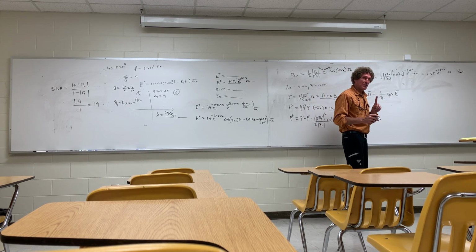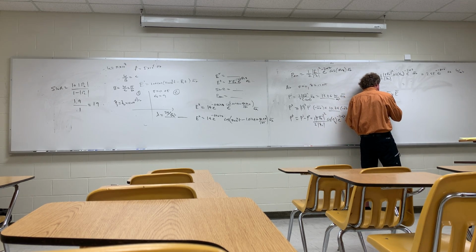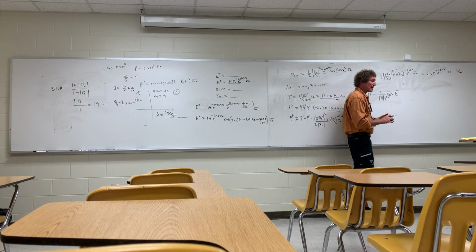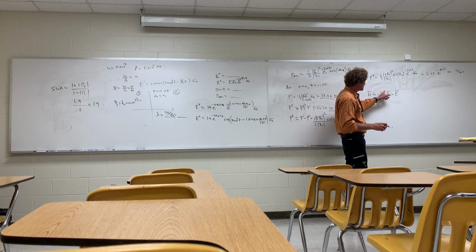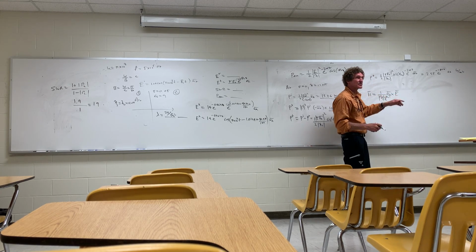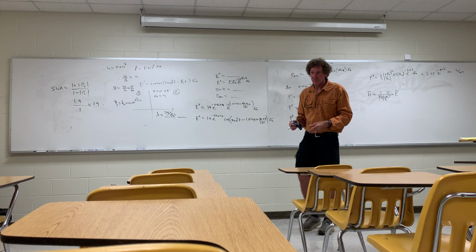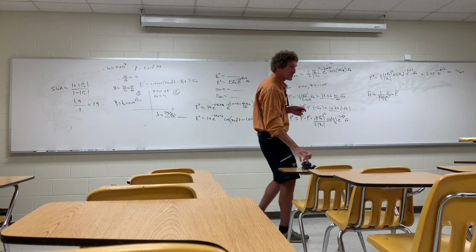Yes, but I'm gonna tell you one thing about this. When you do eta, put a magnitude and then a phase angle. Now, when you take that phase angle upstairs, it becomes negative j. Follow me, class? Y'all see this? Okay, that's real important because that phase angle is going to come up here, it's negative. Then you have this cross, this will give you the orientation of the H field. But now there's a negative phase angle, so no longer are E and H in phase. There's a phase difference when you're in a lossy medium. Maybe we should do that just to make sure you know how.